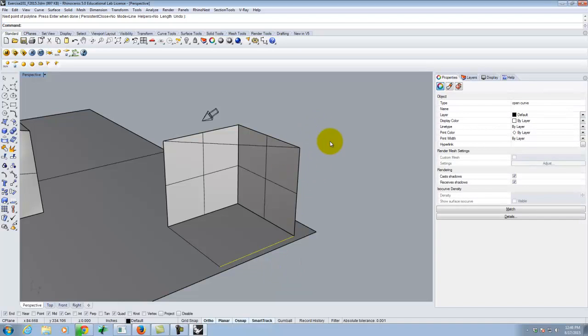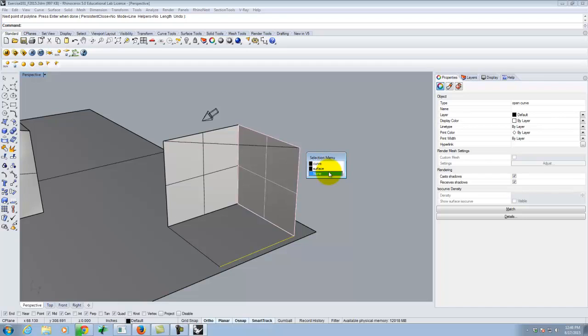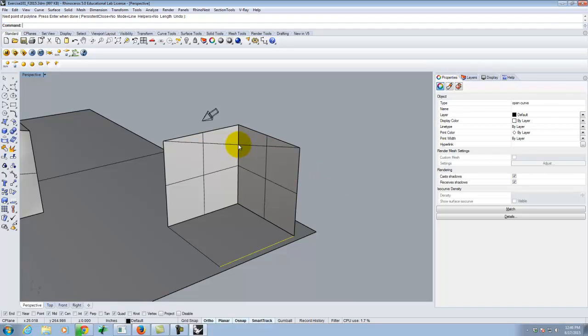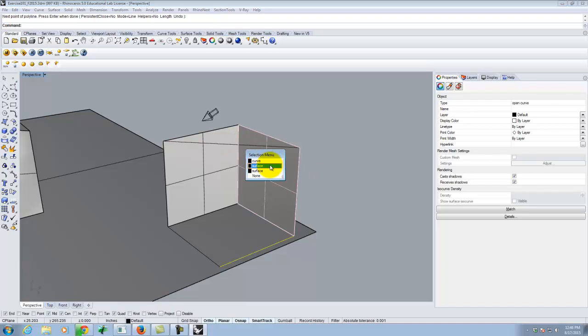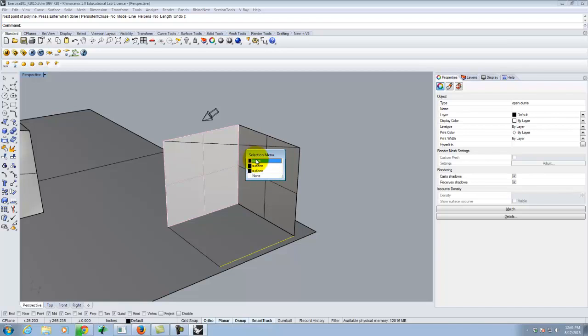Right? And I'll do this again as an illustration. I'm going to hold down Shift. I'm going to pick right on the corner here. And you can see that I can pick either the surface or the curve. Right? If I did this, let me pick none. If I did it right here, right, I'd have 3 options. This curve, the surface, or that surface. You see how it's aware of what objects are around, so it can help me pick. So I want the curve.